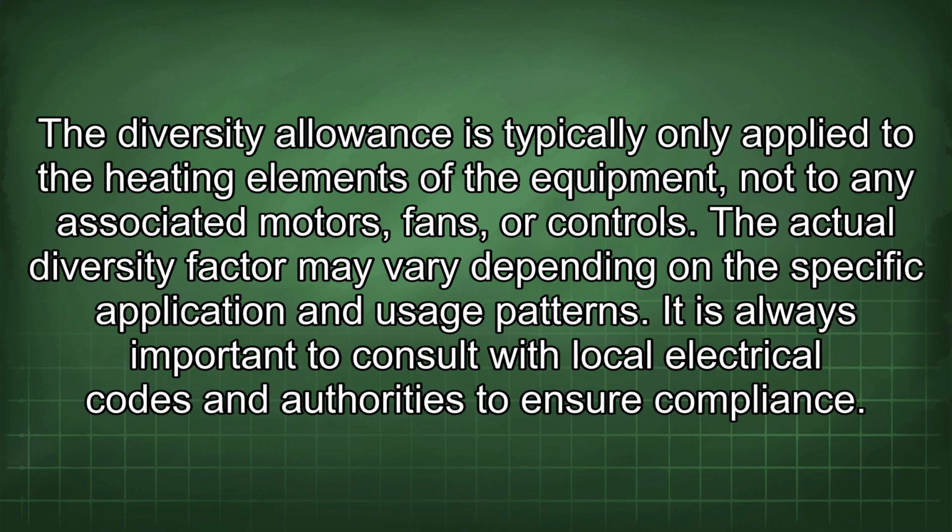The diversity allowance is typically only applied to the heating elements of the equipment, not to any associated motors, fans, or controls. The actual diversity factor may vary depending on the specific application and usage patterns. It is always important to consult with local electrical codes and authorities to ensure compliance.